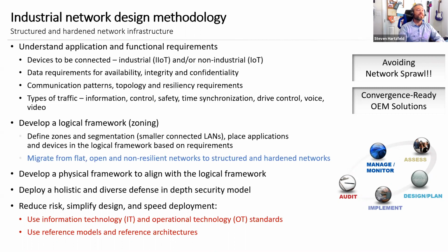The physical framework takes into account that this one part of the network is a half a mile away from everything else. So it needs a fiber connection instead of a copper media connection. It takes into account the footprints of your buildings, the harshness of the different environments, and that these particular subset of links require extra secure connectors and high flex cabling due to extreme vibration, just for example.